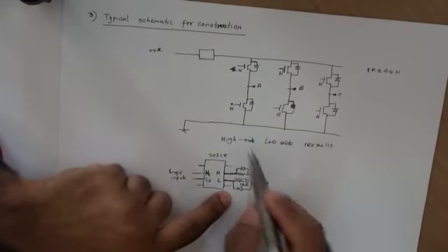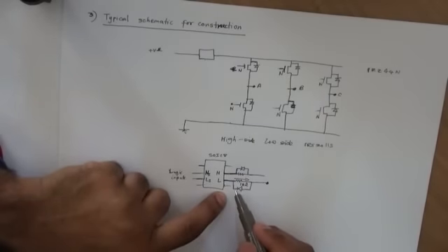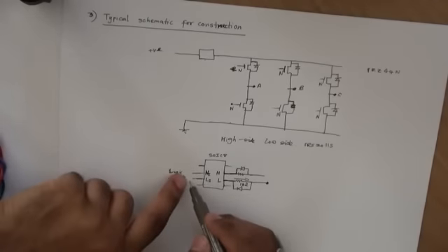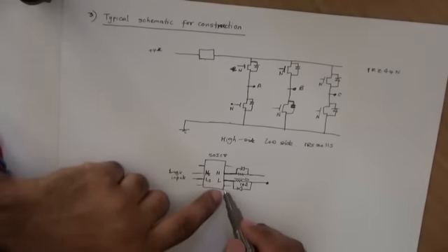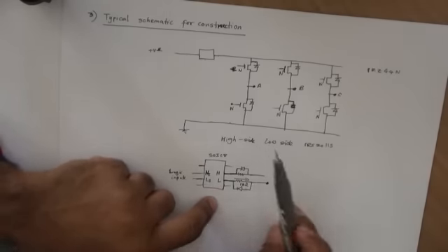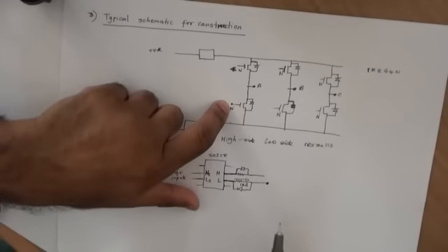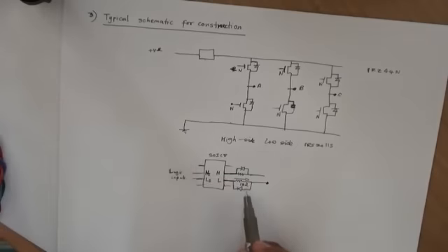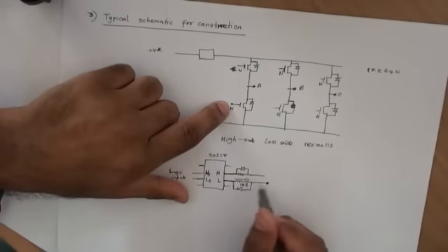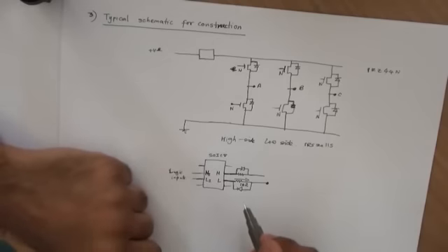The charge that's in the gate flows through the diode and gets shorted out to the ground, because your low side is being brought down by the microcontroller, and as it is being brought down to the ground, the charge flows out of the diode and into the ground, and hence it turns the MOSFET off much quicker than if you just had a resistor, because your MOSFET gate is really a capacitance gate, and your RC will mean that it's discharging very slowly.